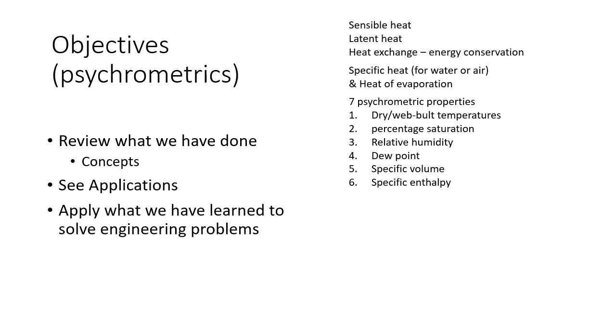Right, based on these three concepts, we looked at 7 psychrometric properties of the air. Right, we start from water and we go into air. We consider air a mixture of vapor and dry air. So therefore, we need 2 variables to define the state of the air. The most common way is to provide dry bulb and wet bulb temperatures. So we have 2, and these 2 are easily measured by sling thermometers.